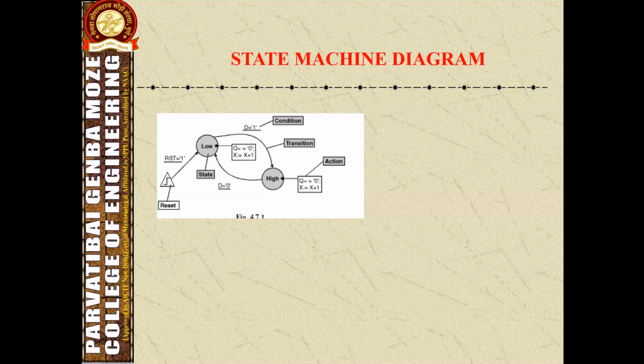The combinational and the registered signals updated in state actions behave differently. Combinational signals are sensitive, or change asynchronously, to the machine outputs because they are updated by the concurrent signal assignment. The registered signals are updated within the machine process, so they can change only on the active clock edge.